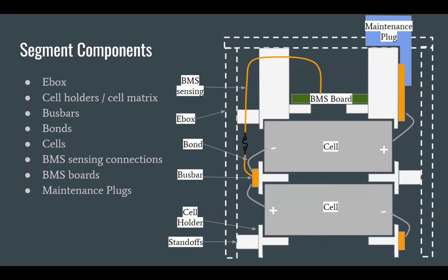There are connections in the battery pack that do need to have interlocks, specifically the main connector for the battery. But the maintenance plugs do not need to have interlocks. There are maintenance plugs you can buy that do have interlocks. We just don't do them. Not having interlocks isn't a safety issue, but I'm just thinking, if we accidentally don't plug one of them in, then the BMS will be happy to turn on the car and it'll read all the voltages correctly and everything will look fine.